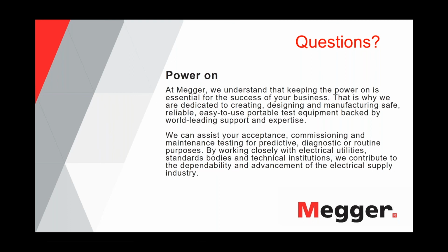If you do a VLF test with the right test parameters, then you will have no problems with water tree induced aging or failures for 2 to 3 years when you pass the test. Because if you would have a critical sized water tree, as Javier showed in the presentation, I repeat, a properly conducted VLF test will rake these imminent failures out of your system. So for the VLF test, you say 3 years, for instance. Some people do 5 years.